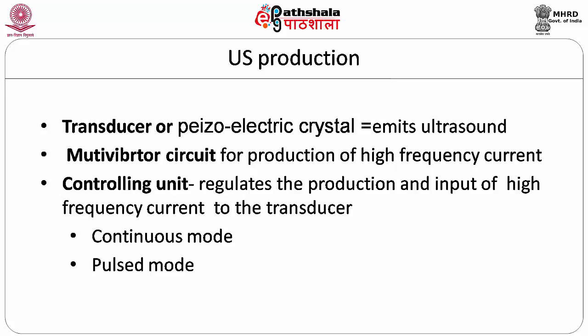The therapeutic ultrasound machine has three components: a transducer or a piezoelectric crystal that emits ultrasound, a multivibrator circuit for production of high frequency current, and a controlling unit that regulates the production and input of high frequency current to the transducer. The transducer consists of a slice of piezoelectric crystal mounted on a metallic plate. It is connected through coaxial cables to the multivibrator unit.